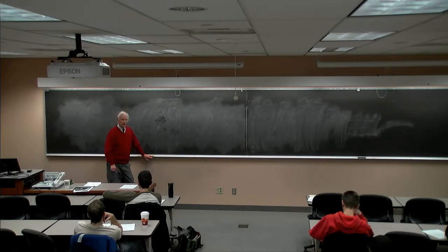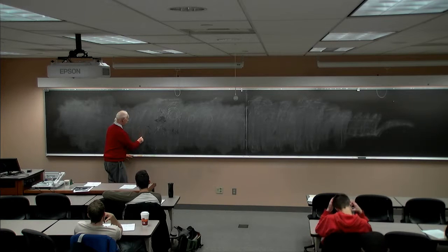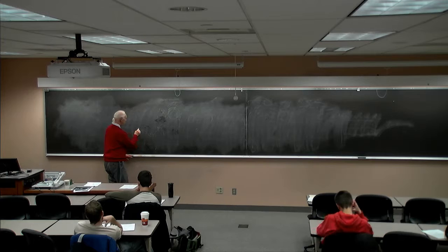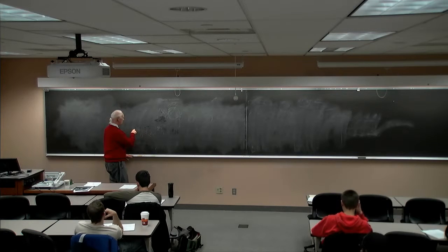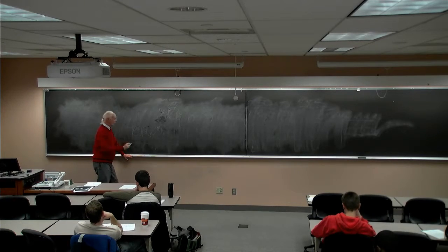And I give you a hint. The hint is that when you get that flux, it's an integral all over the B field dot dS, right? This is equal to the flux, the B, so many Webers per meter squared times the number of square meters gives you the number of Webers going through there. And then the voltage is the rate of change of that with respect to time with a minus sign in front of it and all that.